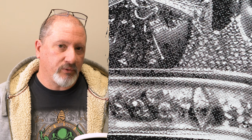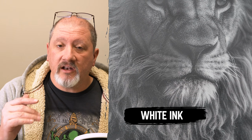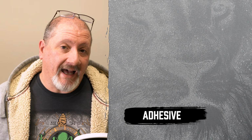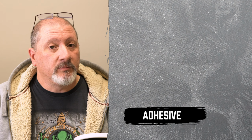Is that dot that it printed out going to grow a little bit? Because we have layers that we're dealing with when we're creating our transfer. We have the carrier that's on the PET film, so that little layer that holds onto the ink and that releases from the film. Then you have the white that you're printing, however thick or thin that white is, and then your adhesive backing. So all of that, when you look at your transfers, has a bit of volume. So that then goes on the shirt. It gets smashed with the heat press, and so you can get a little bit of spread.